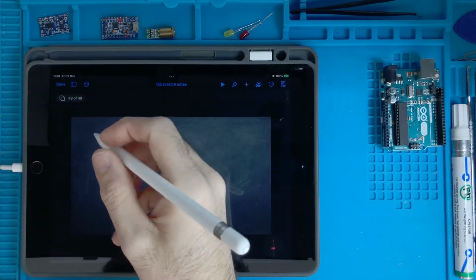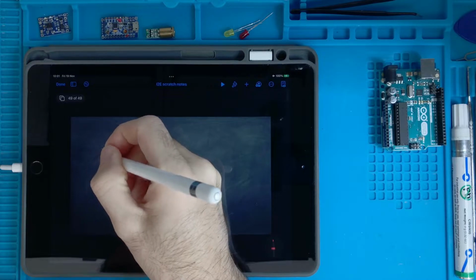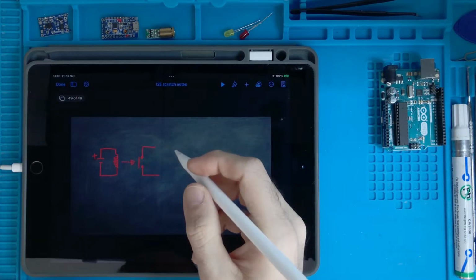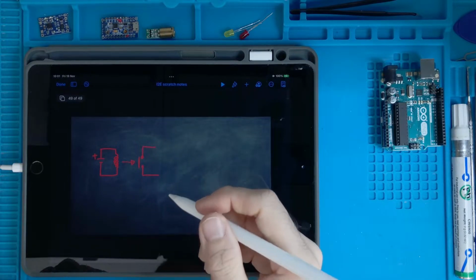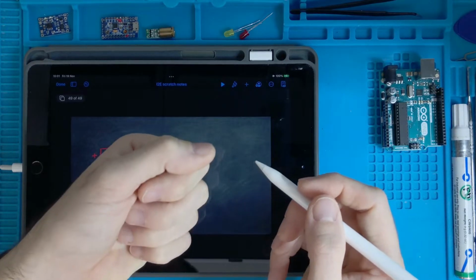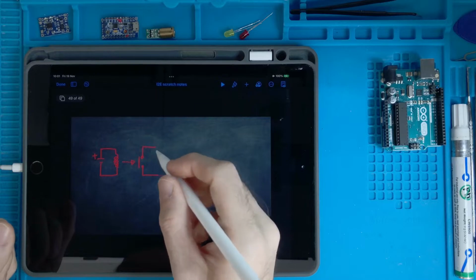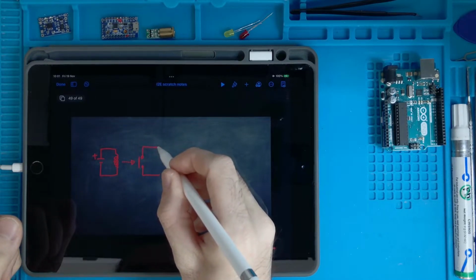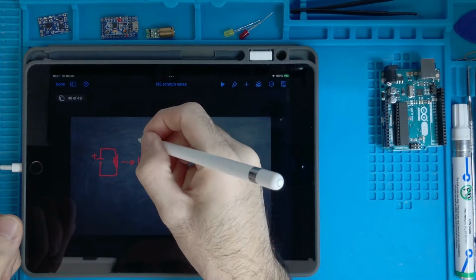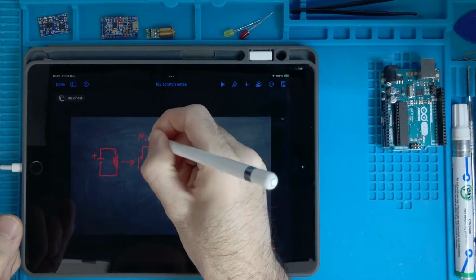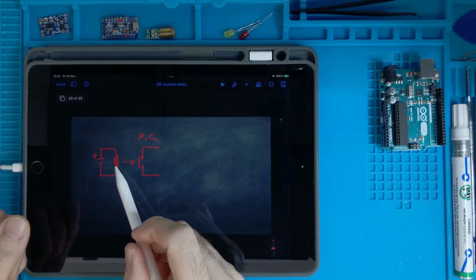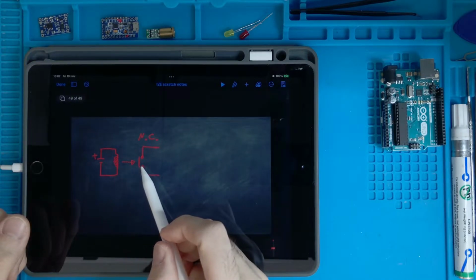So if I connect the battery, I activate this thing, and the lever will open the circuit here. This is a so-called normally closed switch, which means that without the activation of the magnetic field, this thing is closed.